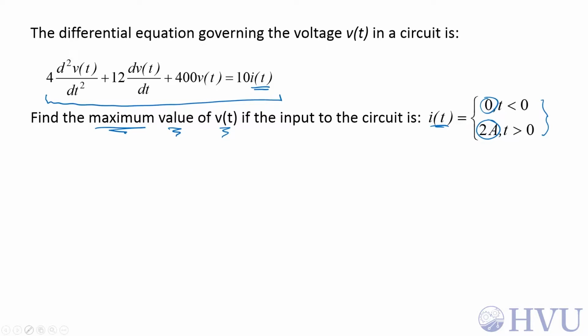Now, rather than explicitly solving this differential equation, what I'm going to do is use the coefficients of the differential equation to infer what the peak value of v of t is. So I'm going to want to convert this to standard form.